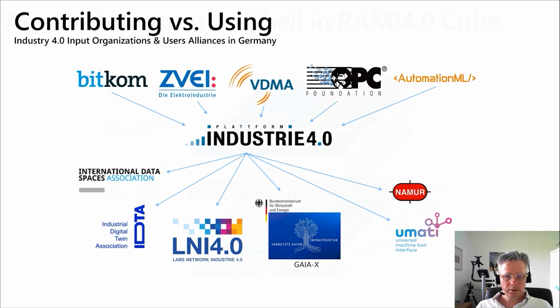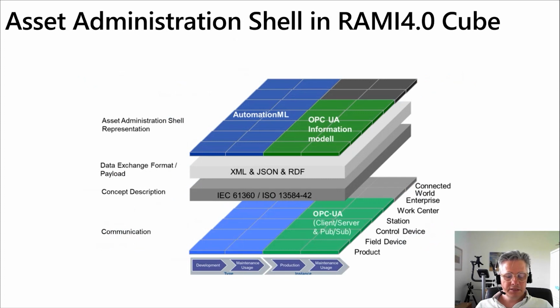So what does that mean in terms of standards for the platform industry for a reference architecture? Well, OPC UA is mandated as the information model and the communication infrastructure for client-server communication. Towards the connected world, towards the cloud, OPC UA has been extended in 2017 with PubSub. So the area in gray here is now PubSub.